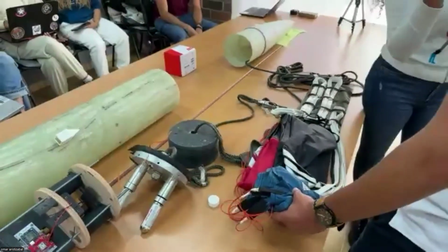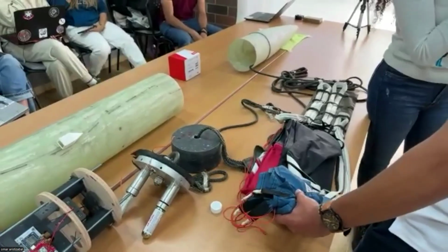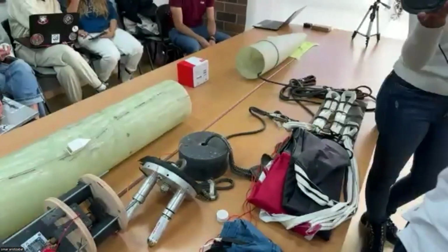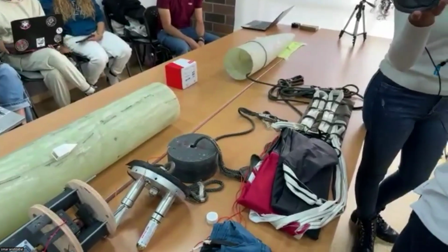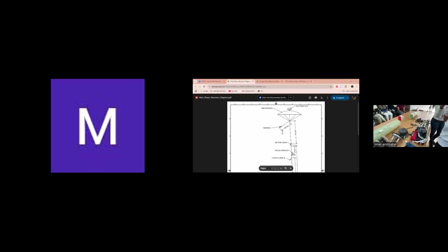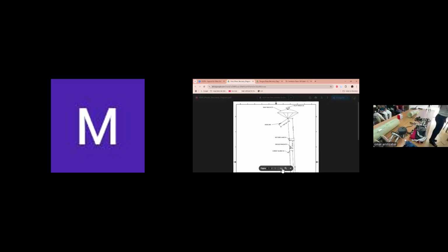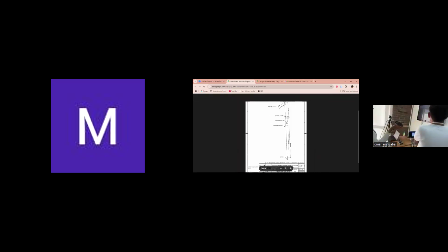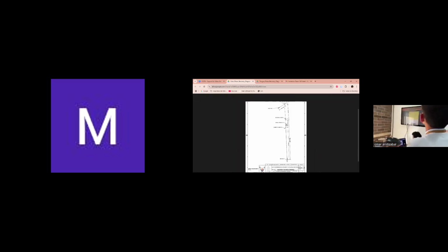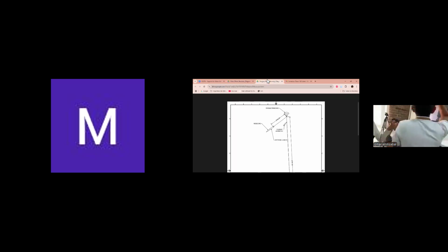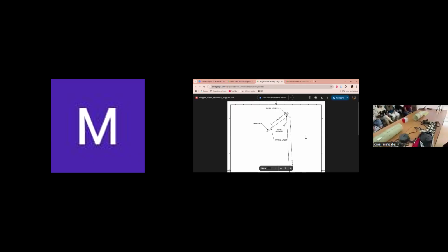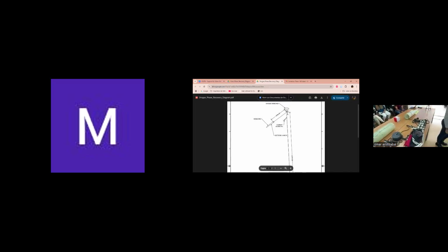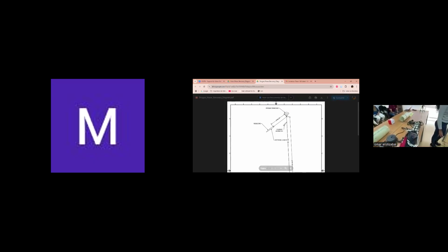If you could share the screen please, to show the diagram. This is how we expect it to work. It is, of course, an ideal case. No, this isn't the diagram, the drogue one, please. Here you can see that the drogue parachute is placed above the nose cone. So we expect that the pilot parachute helps to extract the main parachute and place it above the drogue.